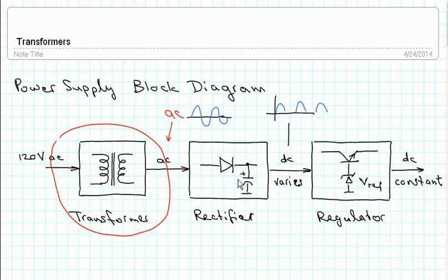And then you use a capacitor, like this one here, in order to compute the average of that voltage. You would have something like a V average, which is the DC voltage that comes out here. And then in the end, some regulator has to be here, which is making that voltage constant. At that point here, the voltage can vary depending on load.